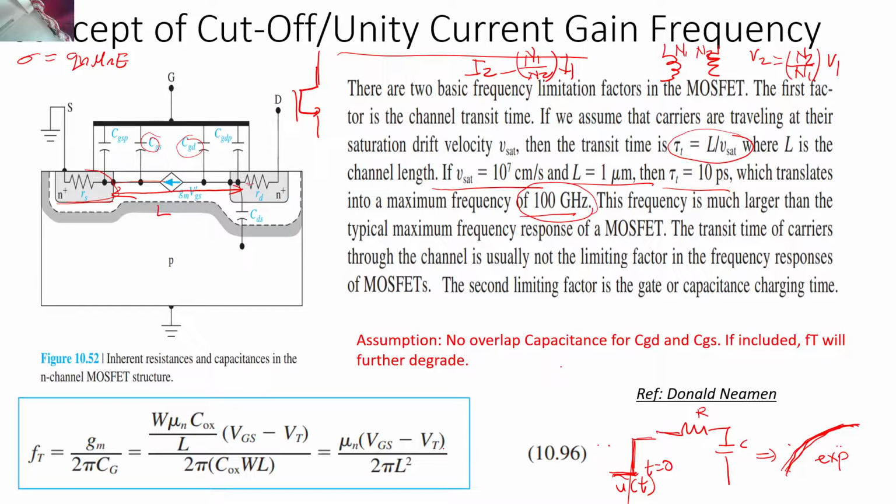But the same cannot be said for the amplifier. The amplifier will give you power gain. The basic job of the amplifier is to give you more power at the output as compared to what you have given at the input. The transformer does not do that job, because a transformer doesn't have power amplification. It can only give you either voltage amplification or current amplification. That's it. Now if you consider this MOSFET, the voltage gain will depend on what you are connecting at the output of this MOSFET and what you are connecting at the input of the MOSFET.